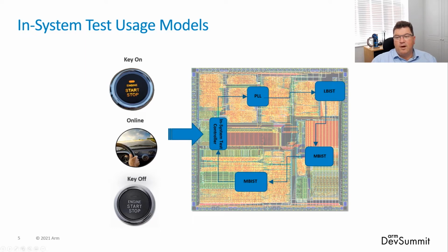is to enable the test to be run whilst the device is in its functional operation. And certainly for the BIST test, the requirement is to take whatever part of the design is being tested offline for the duration of that test. And also typically the BIST tests are destructive. So all of the data that's in that part of the device will be lost and reset back to a known state. However, with the complexity of these devices increasing and the quality standards and requirements, especially with safety critical applications, running online tests is now becoming a requirement.